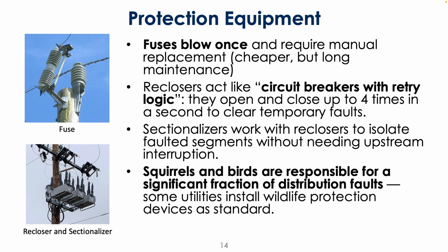The sectionalizers are the equipment that work with the recloser. These are the things that actually count how many times the reclosers are opening and closing. Once it reaches a threshold, it tells the recloser, hey, you've tried to clear the fault enough times and it's not doing anything, so stay open. These systems are usually coupled together.